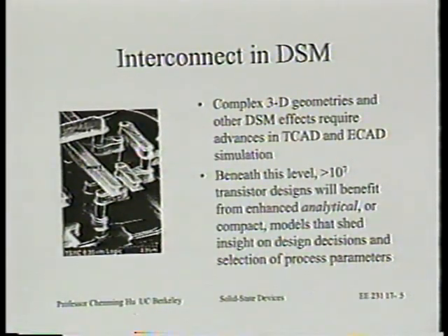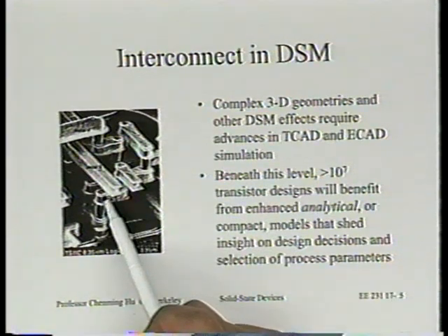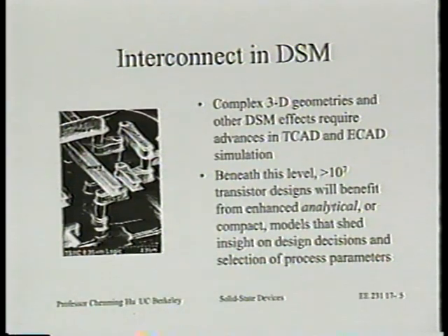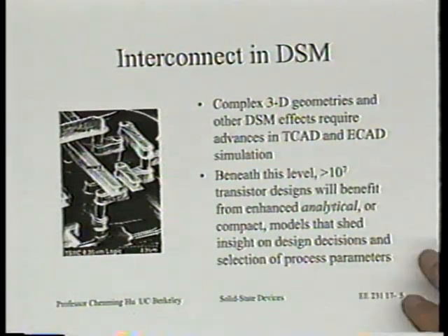That's not what the layout shows. Layout would have shown a square via here, but because of lithography, you end up with a round hole. Okay, so you can see we're coming to very much the limit of lithography. We cannot resolve these corners anymore, right, at this feature size. And if you look carefully, you see those liners, those TiN layers. Do you see that? Yeah? On top and bottom of each metal interconnect, you see these TiN layers, all right? Okay, so this is what you see. We're talking about very complex 3D geometry, all right?